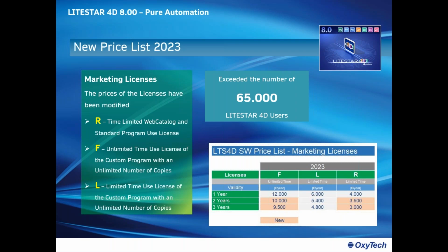First of all, it is a system capable of converting the information starting from an OXL 8.0 file into LDT files, IES files, polar diagrams, Cartesian diagrams, all the color parameters and diagrams, all the photometry parameters and tables like the UGR, etc., straight away. So you don't have to create the different files locally and then upload them to the internet. They are automatically converted by the system. So in this case, the R is the web catalog activation for the manufacturer.